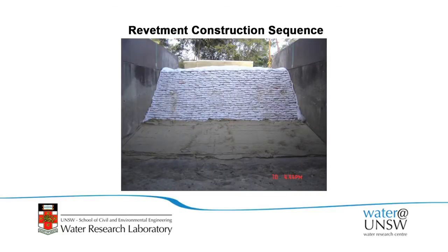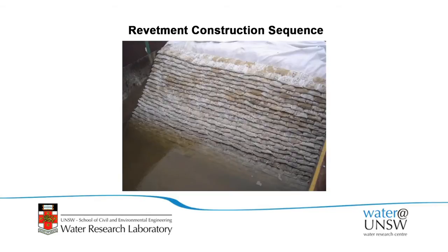This is the beach in front of the structure, and we varied the slope on that, as I said, from 1 in 5 to 1 in 10 to 1 in 20. But as you move out into deeper water, traditionally East Coast Australia, you've got about a 1 in 50 slope once you start going out into the deeper part of the surf zone. But the upper part of the beach is much steeper than that. So that's what it looks like in the flume.